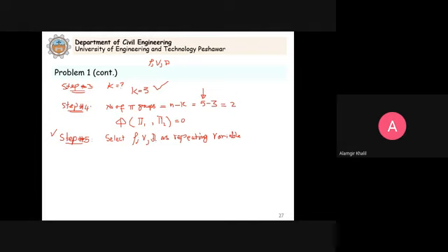So once we select these 3, you will form the 2 pi groups. One is pi 1, the uppercase we use to denote. That will be equal to rho, and because we have to assign the power, A1, then we have D as B1, and velocity as C1. We have 2 groups, so A1, B1, C1. You can use X, Y, Z, no problem.